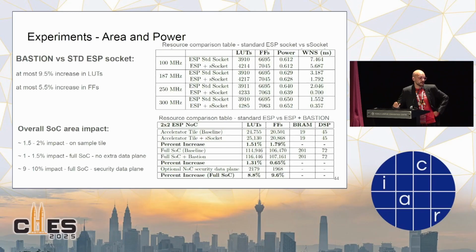Access control for us is integrity and confidentiality. The system itself is a shared memory or shared resources, and before this project a tile could access all of it: all of the IOs, all of the memory from different tiles, privileged or anything. We don't want that. We want to let a tile access just a reserved area of the shared memory. We have the logic that enforces that, with management coming from a trusted entity. So it's not cryptography.